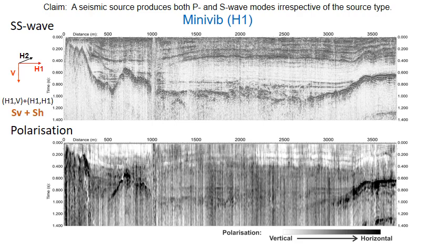In white, we can see that the vertical polarization mostly occurs in the first 300-400 milliseconds, and the deeper sediments are more horizontally polarized in darker gray and very horizontally polarized in black, as the high reflection amplitudes correspond to the sediment-bedrock interface. This is a new approach for understanding shear wave data polarization that could be pursued with even more research.